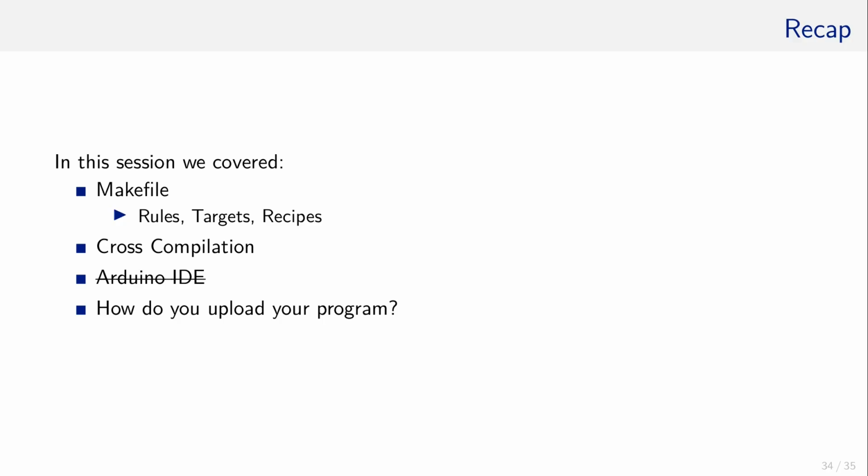In this session, we learned quite a lot. First, we studied Makefiles, their rules, targets, and recipes. And we did not only study them, we directly applied the learned topic and utilized the Makefile to cross-compile our source code for the Atmega MCU. With that, and with the introduction of AVRdude as uploader, we can now ditch the Arduino IDE and write most efficient program code. And higher efficiency means faster execution times and longer battery life. But before going there are some topics that we have to examine first.